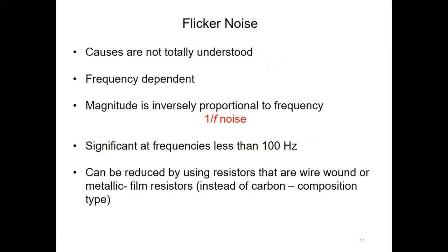And the third one is the flicker noise. The reasons for this flicker noise are not totally understood, so we cannot say, like with the thermal noise and the shot noise, any particular way why this flicker noise is there. And this flicker noise is frequency dependent. Both thermal noise and shot noise are not frequency dependent, but the flicker noise is.